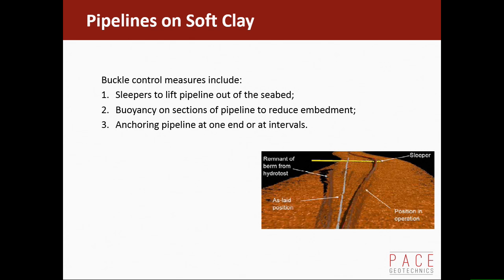So another way of doing that is actually just to put some buoyancy on the pipeline so that you lift it out of the seabed a little bit. Or if it's walking, you can anchor it at one end, or in some cases at intervals along its length, to try and stop it actually walking along the seabed.